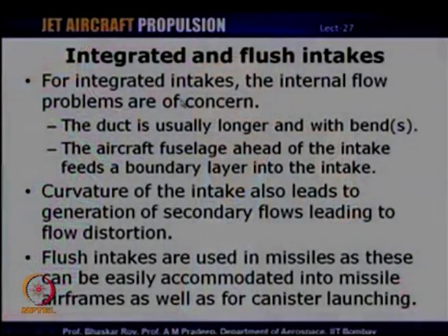Now, the other two types of intakes I discussed, the integrated intake and the flush intake. In an integrated intake, we are more concerned about the internal flow problems, as compared to podded intakes, where we are concerned more with the external aerodynamics than the internal. In integrated intakes, most likely you would have a longer duct with one or more bends.